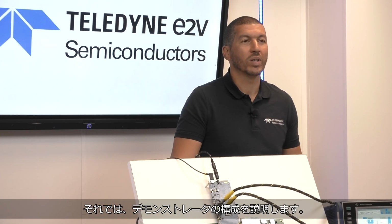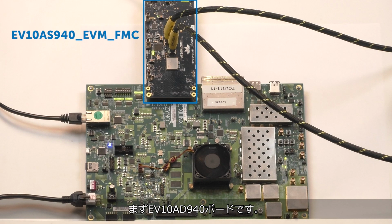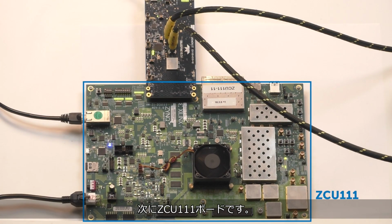Now, what are the elements of the demonstrator? The demonstrator is composed of three elements: the EV10AS940 ADC board, capable of sampling at 12.8 gigasamples per second with 10-bit resolution; the ZC111 board, which hosts the FPGA cores for ADC testing, DVB-S2 detection, and partial demodulation.